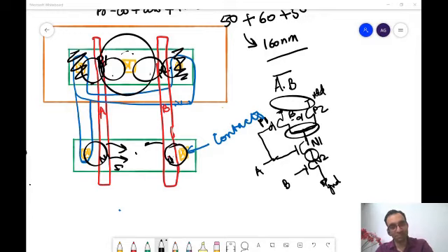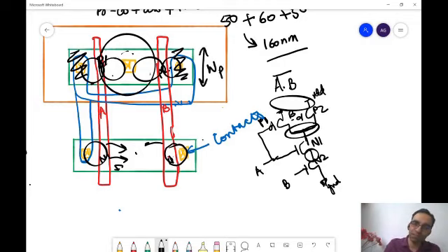Measure the width of the PMOS and NMOS, because we are just running the poly over the active region. Over there, the width was predefined in the schematic, and then we went to the layout directly and generated it. Here, when you are making these active rectangles, you make this as width P and this as width N. Okay, so we are supposed to measure that with a scale, right, sir? Yes. How else would you ensure the accuracy?